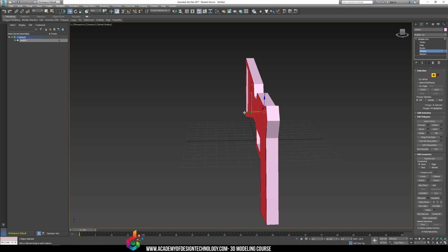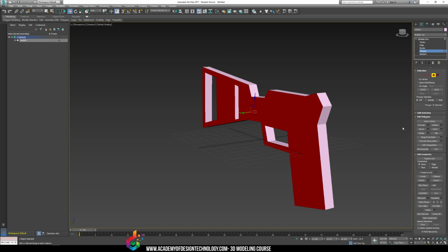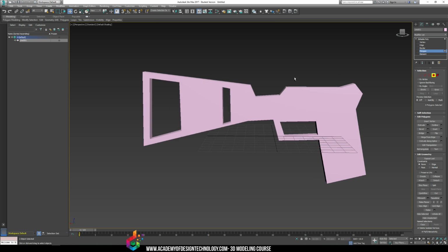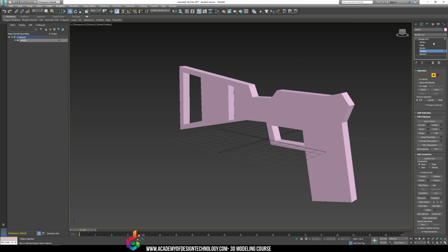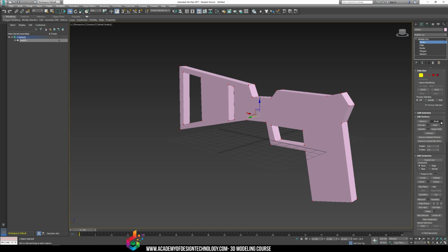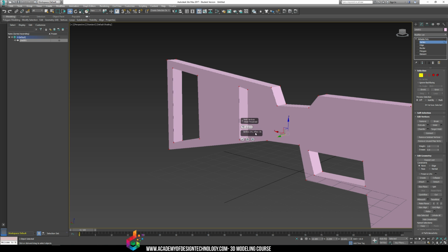I'm going to copy this side of the face over to the other side just by holding shift and using the move tool. Clone the element. I'm going to flip it. And then I'm going to weld it as a last step. Make sure everything welds together. Make sure my numbers change enough, like before 84, after 56. Sounds like a good weld to me.